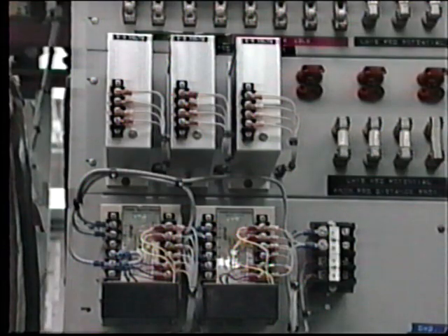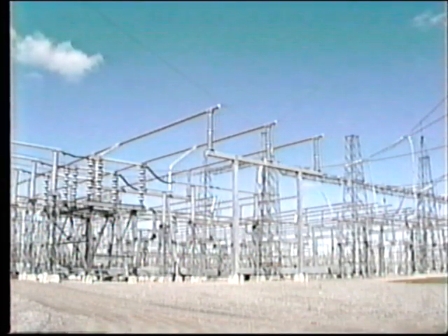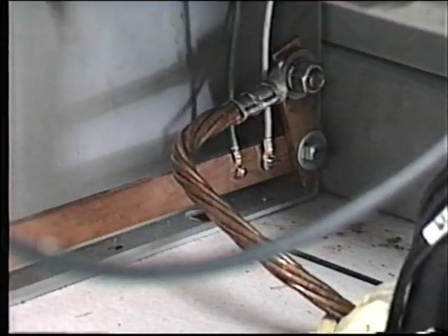In some installations, the transducers are independently mounted adjacent to their associated measuring devices, but it is more common to mount all or most of the transducers in one panel and hardwire these to their respective terminals at the Scada panel. These signals may be subject to serious interference from electrostatic or electromagnetic surges from the power equipment. So special arrangements are usually employed for shielding and grounding. Make sure that your specific installation complies with its particular design requirements.